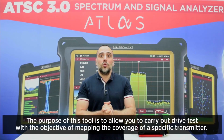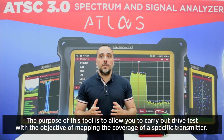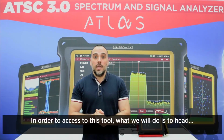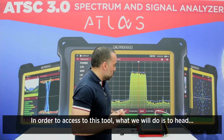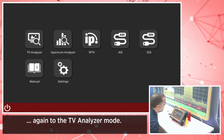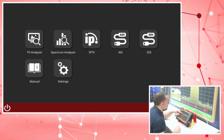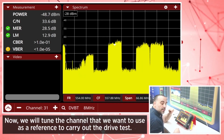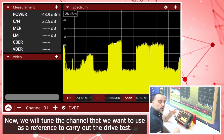The purpose of this tool is to allow you to carry out drive tests with the objective of mapping the coverage of a specific transmitter. In order to access this tool, we will head again to the TV analyzer mode. Now we will tune the channel that we want to use as a reference to carry out the drive test.